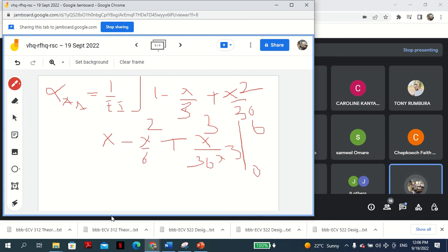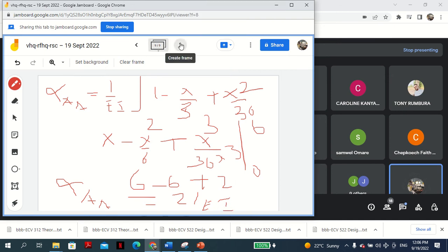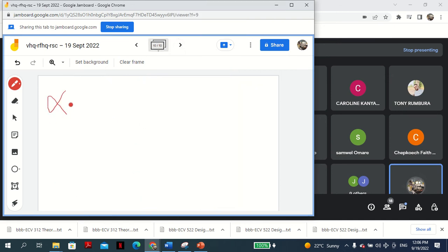6, yeah, so that's correct. So therefore, here you find alpha AA. If you solve, you find this is 6 minus 6 plus 2, and then alpha AA is actually 2 over EI. Without doing a lot, if you want, you can repeat for alpha BB, but you'll see by common sense alpha BB is the same because the geometry remains fairly the same. So alpha BB is also 2 over EI.